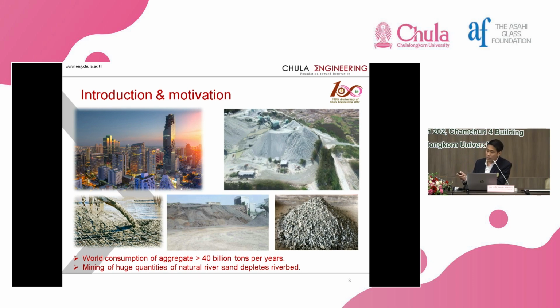And if we look at it a bit closer, this is how it looks. It's not very fine. The gradation is such that some particles are quite big, so you can see them by eye, and some look fine, like powder. So the distribution of these materials is quite tricky, because if we use it in concrete, we have to make sure of the size. It's at an intermediate level, not big, not too small. So we have to look at how we can deal with this to make sure it doesn't jeopardize the good properties of the concrete, especially in terms of safety.